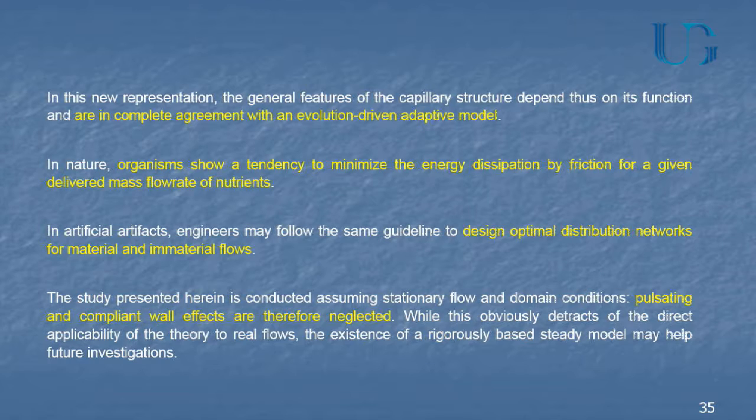We can build a branch heat exchanger according to this law, which I gave you, but the function of that heat exchanger is not to supply blood, it is to subtract heat. But fortunately, the law of heat diffusion and mass diffusion are the same. Fick's law of diffusion is similar to Fourier law of conduction. Okay? So the equations remain the same formally. There are different coefficients, of course. So we can apply this theory to the optimal design of heat exchangers, to see if we can build better designs than we can build with constructal theory. Okay?